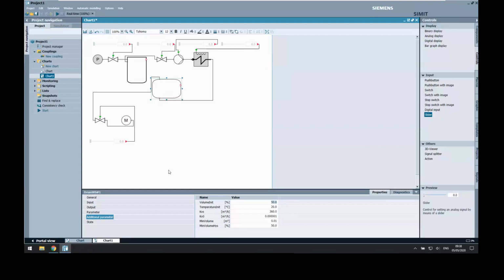Then we have our drum, and I guess it would make perfect sense for the drum to be empty, because we don't want our steam container to be half full of water at 20 degrees, do we? So 0 here, 20 degrees, yeah. So this is the temperature of the tank itself. Now if you start pumping the steam, and if the steam is, let's say, around 100 degrees, it will probably cool down quickly in the tank and turn into water. I don't want that, so just to be on the safe side, let's make it a bit warmer.